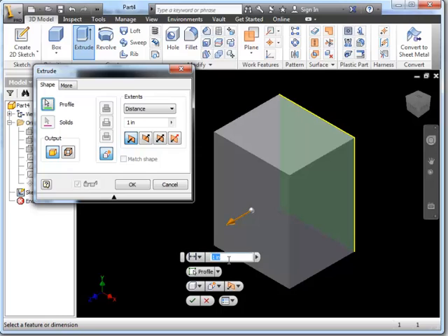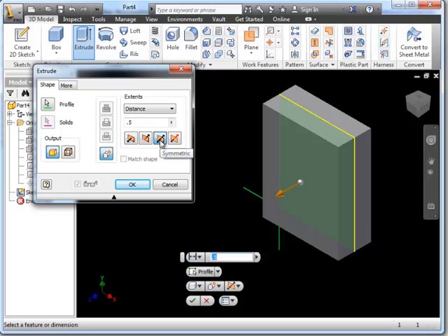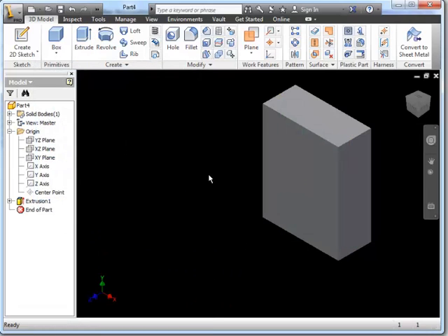I'm going to finish the sketch, select Extrude, and you can see that it's showing me an extrusion. It's defaulting to 1 inch. What I'm going to do, I'm going to change this to 0.5. I'm going to do something different. I'm going to use a different solution on this. This solution right here is called symmetric. And what that does is it takes the plane that the original rectangle is sketched on, and it extrudes to either side of that plane, and it will take my 0.5 and put half on this side and half on this side. So there's 0.25 on each side. I'm going to select the check button for OK, and there it is. It builds my first object.